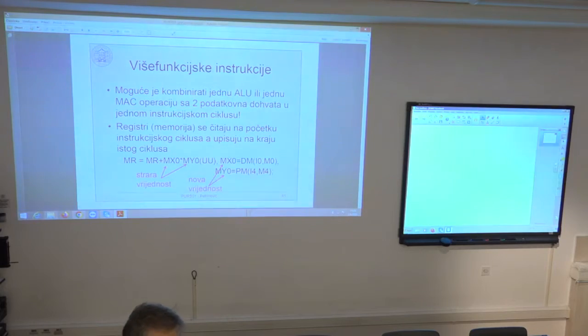So this M0 register can be, for example, initialized to 1, to +5, or to -7, whatever. So I simply initialize this modifier register with some value, and then after fetching, it is a post-modify of the address pointer. So after fetching, the address pointer is modified with the value in the corresponding modification register.